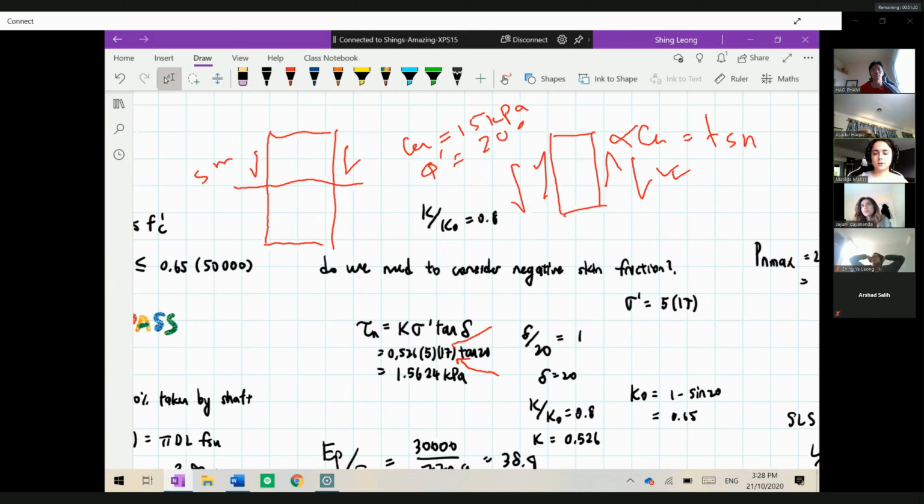In a cohesive soil, undrained is sort of like the short-term effect, I'd say. The pore pressure hasn't dissipated yet, and drained is the long-term effect, when it's dissipated. Yes. So if you look at this negative shaft resistance, which is working on the clay, and that